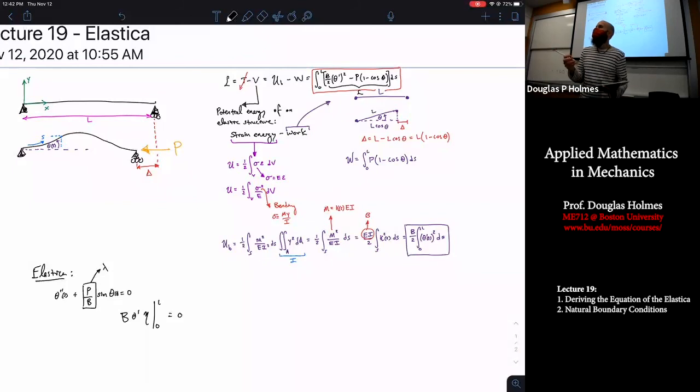And what we know, if you think about things in terms of simple support, what does a simple support boundary condition mean? It means that the angle could be any arbitrary value at the end there. The angle at the end of the beam can be any arbitrary value. And the only way that can be is if there's no moment acting on that beam, resisting the rotation of that end of the beam. And look, here's what we have. We have an equation here that says the product of this thing times this thing has to be 0. And so what does that tell us?